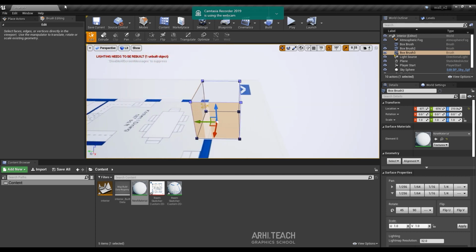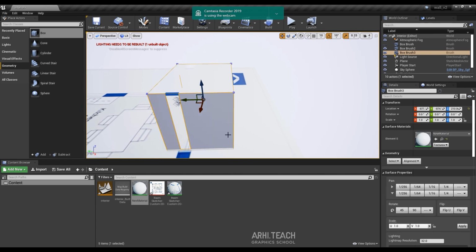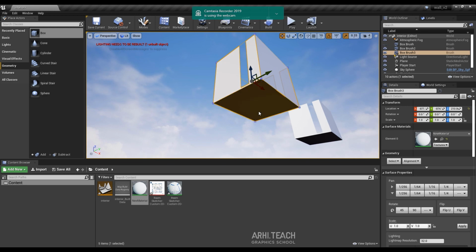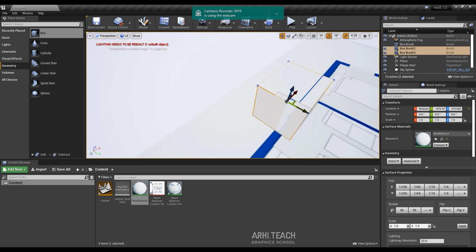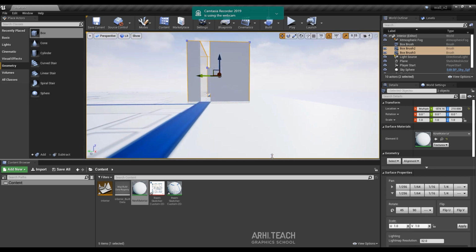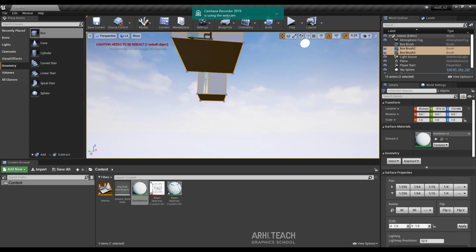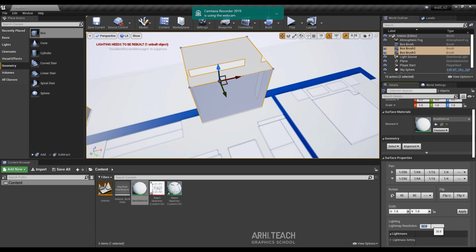We had better now select these planes and assign the best unwrapping quality to them right away, so that they are identical when we copy them now. So I don't have to change the copies later. Here in Lightmap resolution, the lower the value, the better the unwrapping quality will be.